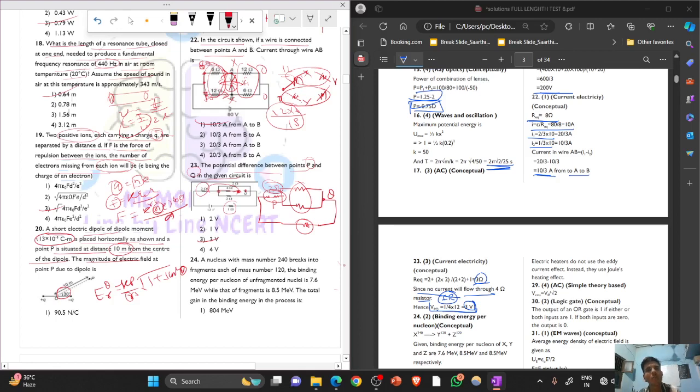Okay, there is no use of this 4 ohm resistor, because the wire is simply in this way. You can take it in this way. And there is no potential difference or anything like that. It is not connected anyway. So there is no use of this 4 ohm. There will be no 4 ohm. There is 2 ohm and the circuit is redrawn in this way.